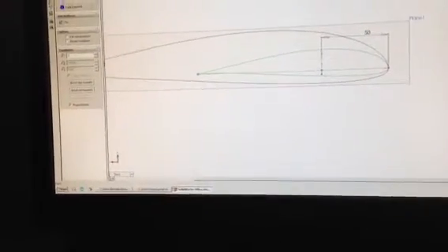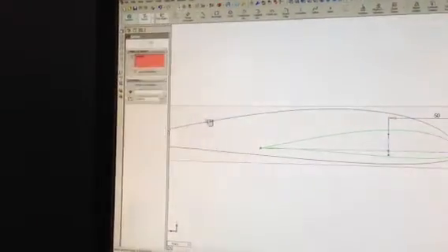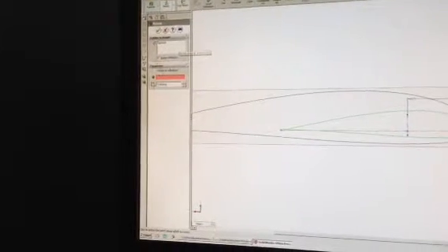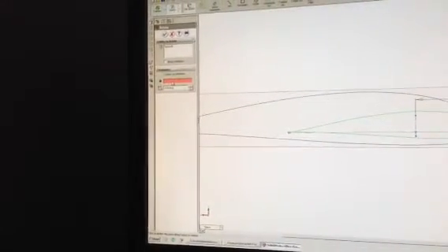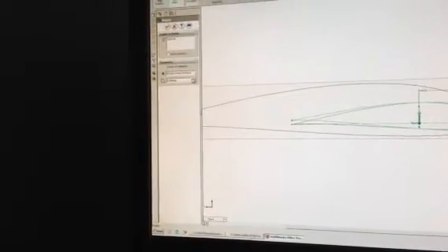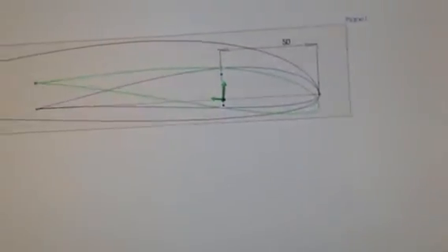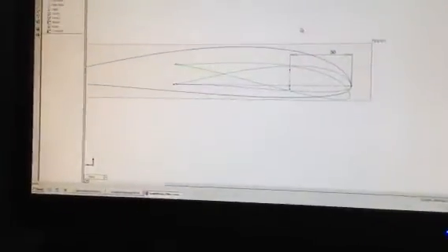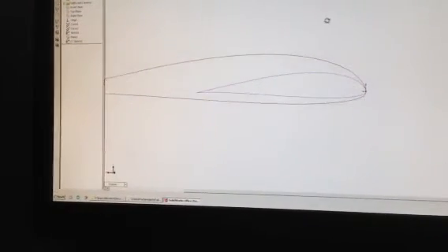So update the sketch. I'm going to right click on the sketch and edit the sketch. So I'm going to select my curve again. I'm going to go Tools, Sketch Tools, Rotate. This spline is already selected. I'm going to unclick Keep Relations. Center of rotation. We're going to select our point. And oh, there we go. We'll just click the little arrow button until it increases. So there we go. It's more like it. So we're okay. We now have our sketch, so we'll update.